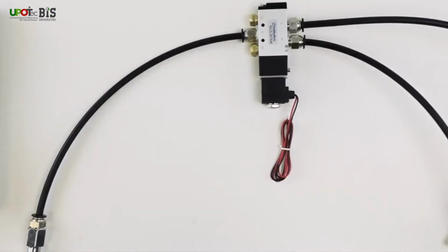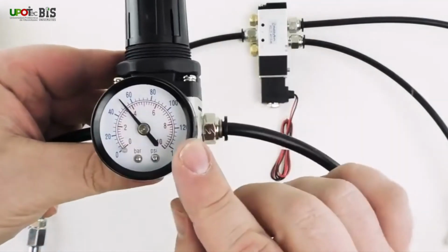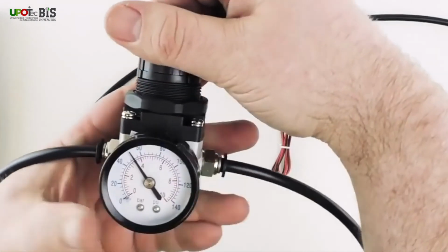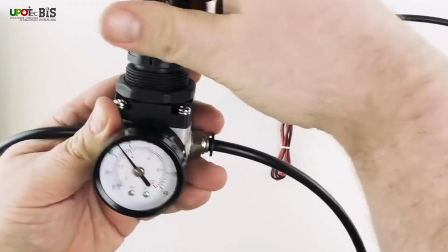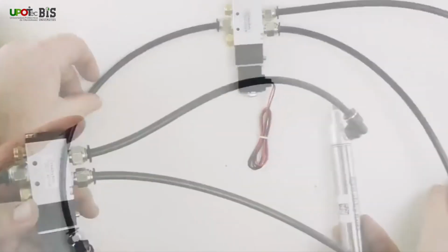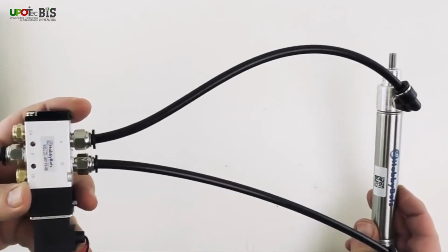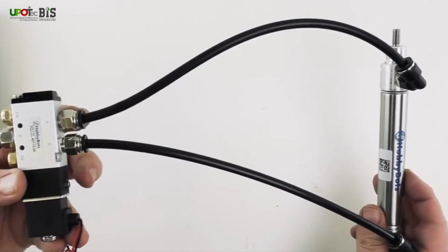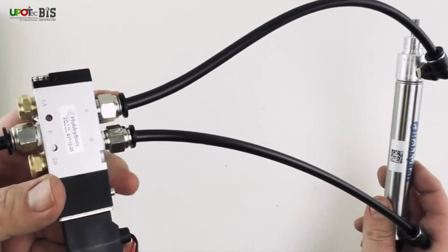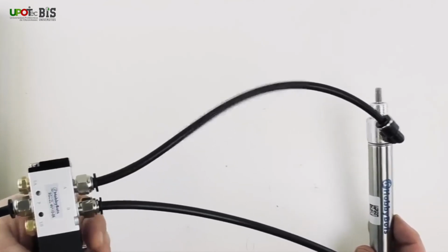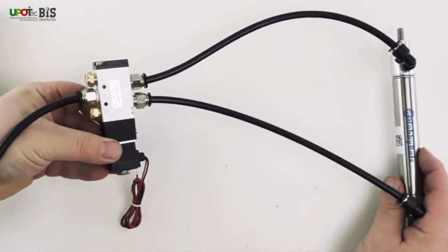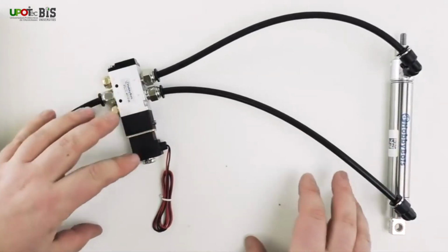Now the last thing we want to do before we connect air to our solenoid is check our air pressure. Your compressor may have a regulator like this one. Turning the dial at the top of the regulator will adjust the air pressure. Somewhere around 40 to 50 psi will be fine for most pneumatics. We can now test our solenoid to make sure it's operating properly. You can see that there's a small silver button here on the edge of the solenoid. We can go ahead and depress that and it will actuate our cylinder. Alright, that's working fine.